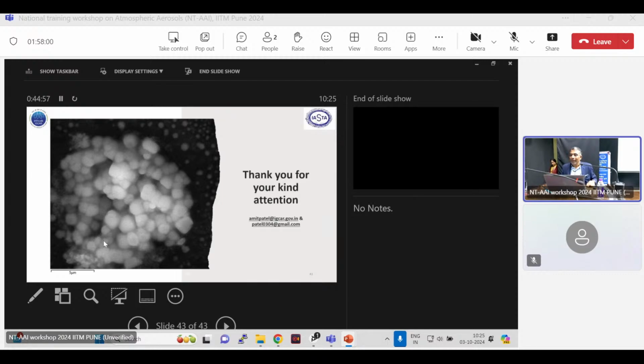Third is the gas. If atmospheric air is there, it can create ozone, or since nitrogen is there, if we are using atmospheric air, NOx can be generated. So there is gas inhalation also. So your chamber should be perfectly leak tight.